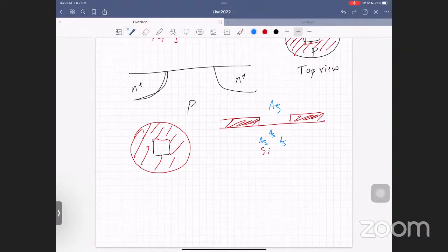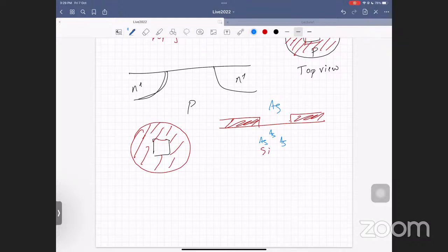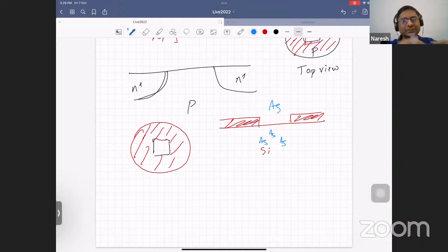I have a question. In FinFET, we have better electrostatic control, right, sir? How is it possible? Okay. So see, a traditional MOSFET is flat, like this. Now you're applying voltage only from the top. But a FinFET is a three-dimensional device. So this is my silicon, and I have an oxide around it, and I apply a gate around that. Now if the fin is very, very thin, then I can have a channel on this side, and I can control much better when you have a three-dimensional structure.